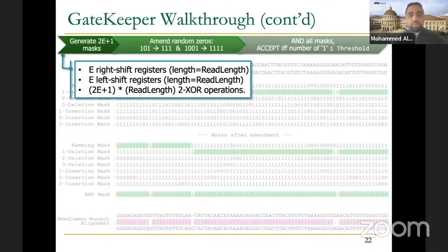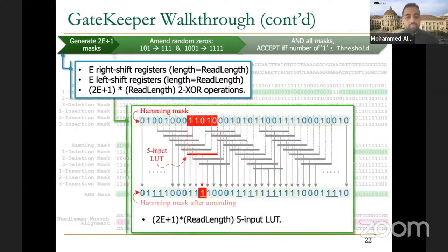So it's up to you to do this kind of optimization. Or you can do it totally independent of each other. So for example, you can shift again in the next step the query by 2 steps, right? Or you can shift it by 1 gradually. It depends on which one will provide better throughput as well as better resource utilization.